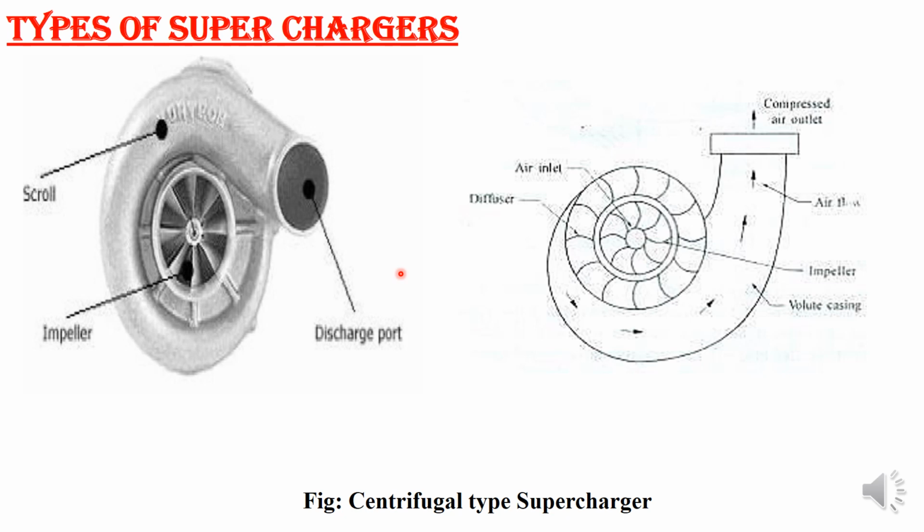About 70 to 80% isentropic efficiency can be achieved with a pressure ratio of 2 to 1, and a very high pressure ratio can be obtained in a single stage. The weight of the compressor is usually 0.6 to 1% of the dry engine weight. Mechanical efficiency we can achieve is around 90 to 95% when compared to a good design. So these are the advantages we get on a centrifugal type of supercharger.